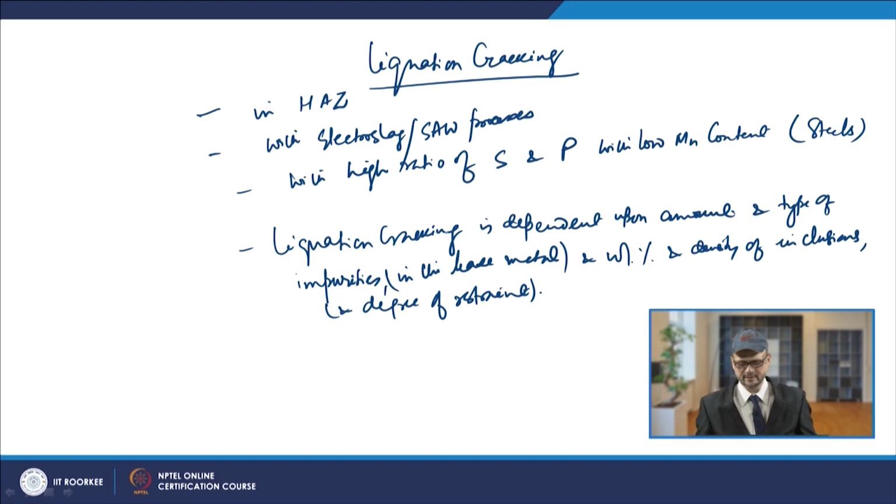So, basically you will have the high energy welding processes, and they increase the susceptibility to these problems. The dwell time in the high temperature zone is also very important. That is why these high energy welding processes basically aggravate liquefaction cracking during the welding. Now, this is about liquefaction cracking.